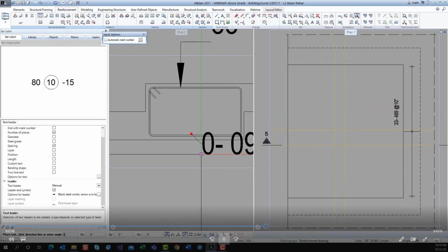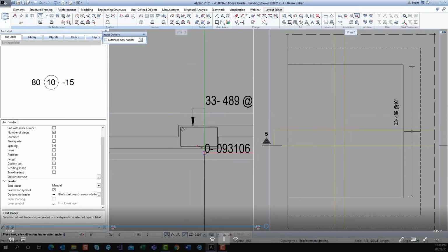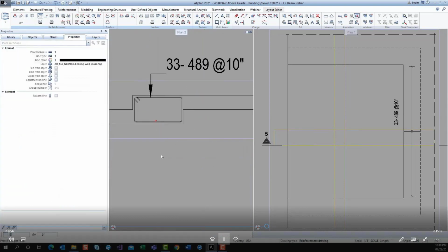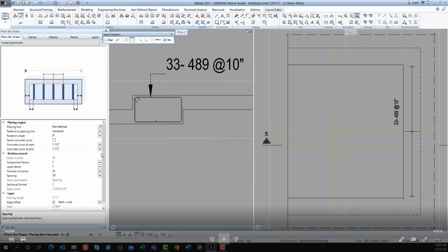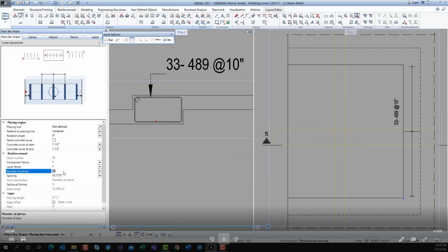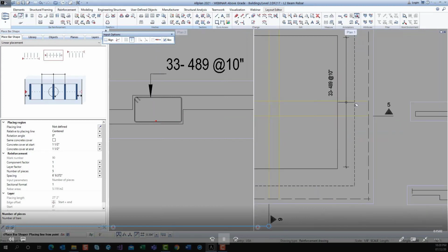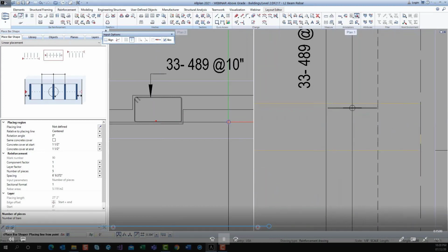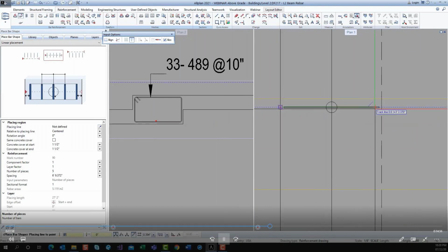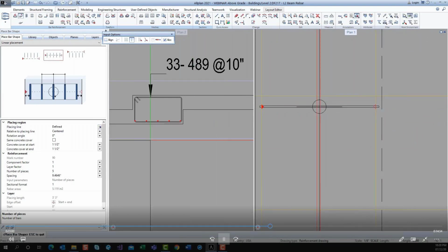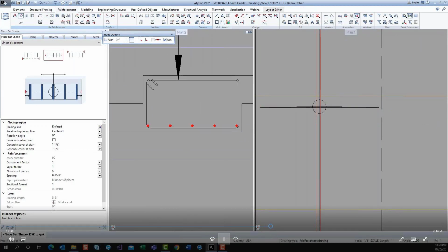So after I place the label, I'm going to make sure when I place my range, it's centered to this beam. So by centering its location and placing the range, it now knows I'm going to do a 2 foot protrusion or 2 foot embedment to either end of that. Okay. And then it's going to make sure it's in the proper location. It's going to walk me through, okay, what's your range, place my dimension, place my label, and so on. That's what it allows me to do.